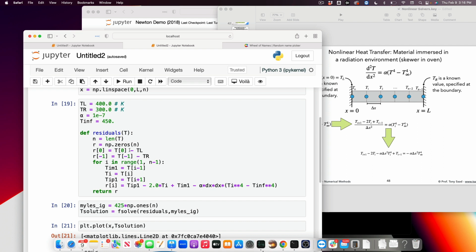Yes, Ethan. If we only had one temperature reading, like say we only knew the temperature where some thermocouple was in our system, and it was in the middle of it, would we still be able to solve the system? Yeah, well, that's a problem for ODEs. It will be ill-posed. You need to know enough boundary conditions that is consistent with the order of the equation. So this is a second order differential equation, so we need at least two pieces of information so that we can close the system, right? It's those endpoints, right? There are two points, one on the left, one on the right, for example, that you need to know, right? Those become more on the modeling side. With the numerical method side, you kind of have it well defined, right? That's what we're doing here. Yeah, yeah.